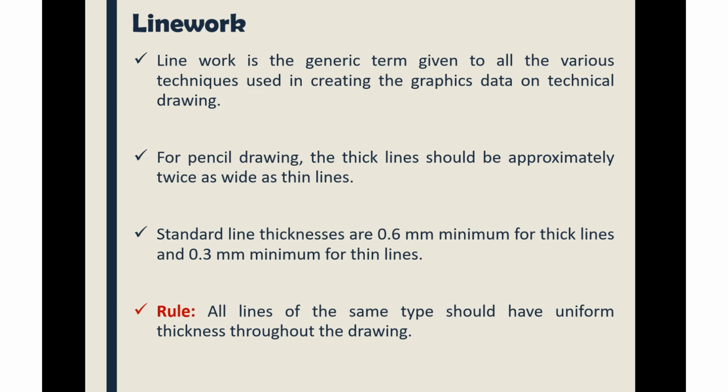For pencil drawing, the thick lines should be approximately twice as wide as thin lines. The thick lines are expected to be your outlines, while the thin lines could be your dimension lines or other lines like hidden lines. But construction lines should be far thinner than the thick lines.